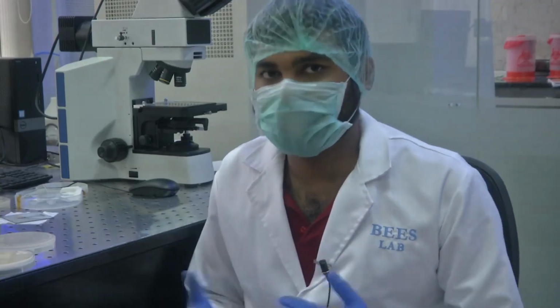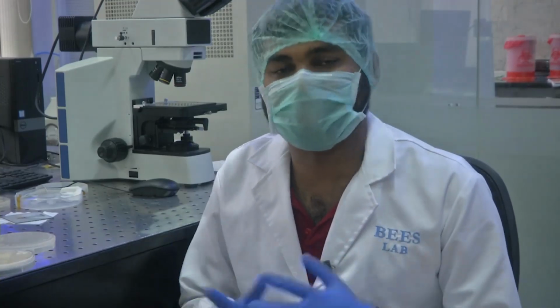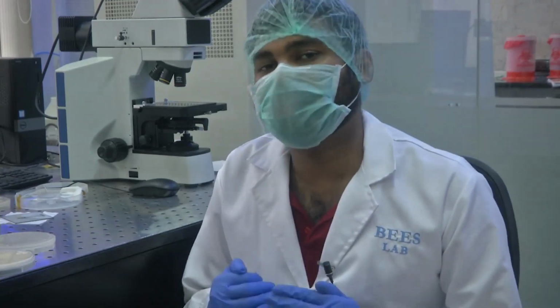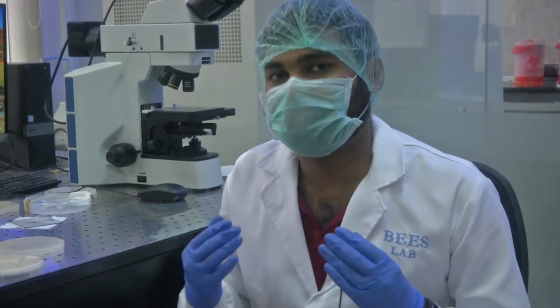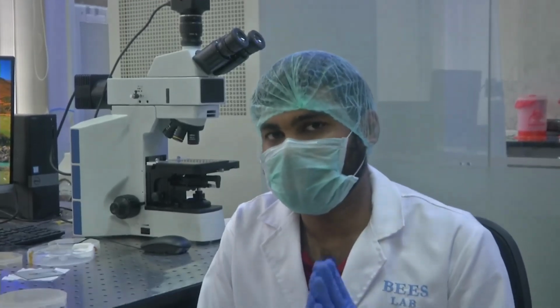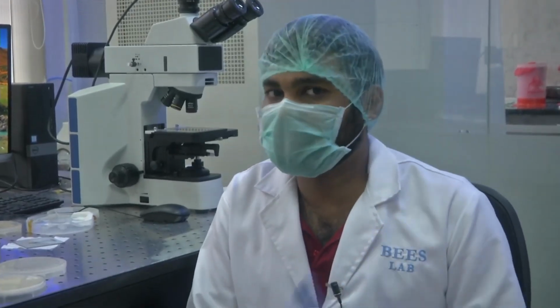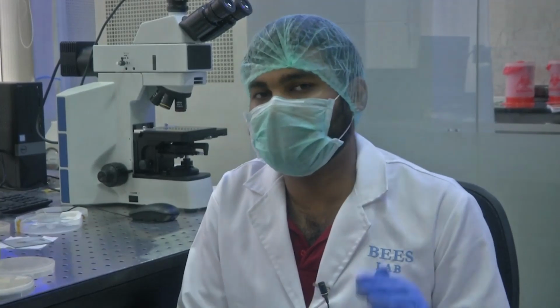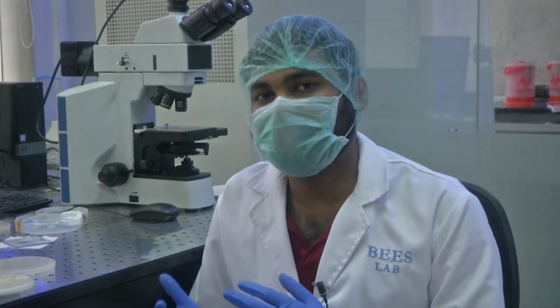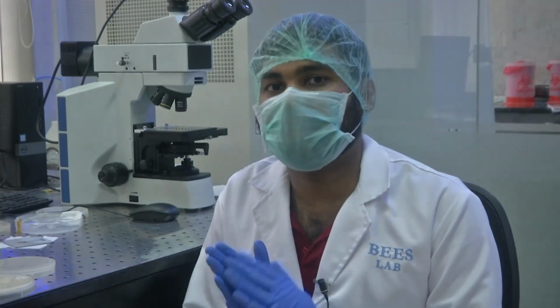So for electrodes, for interdigitated electrode structures, as you might have seen in the lectures, for IDEs, it is good to have a thicker material. So now you have seen two cases. If you are making a micro heater, it is good to have a thinner deposited metal layer. If you are making an IDE structure, it is good to have a thicker material layer.